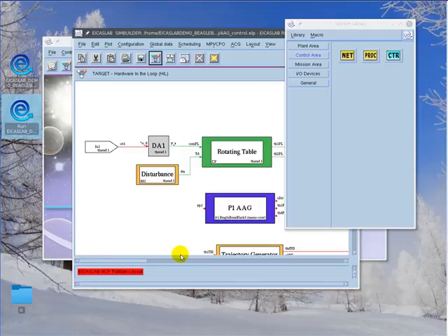In the system layout, you can see that the processor is assigned to the BeagleBone Black 1 hardware target, which is a BeagleBone Black board. This means that the routines and threads it includes are no more executed by the EICASLAB RCP platform as previously done during the RCP operation, but the code has to be generated, exported, and executed on the external target device.